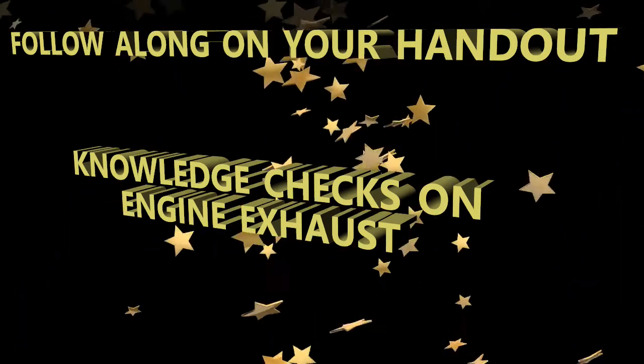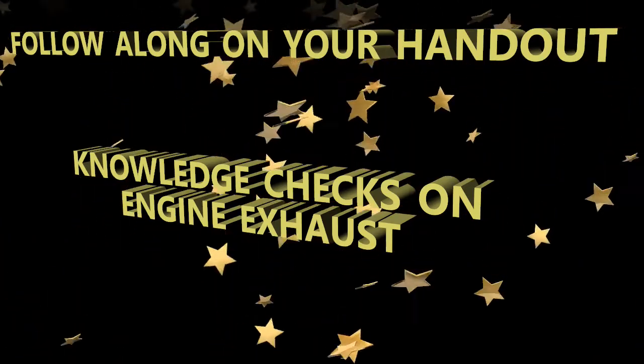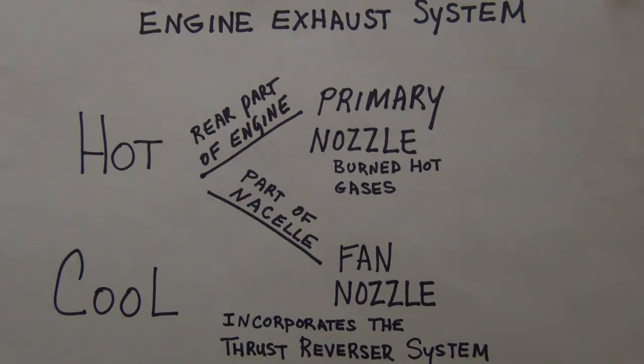All right, I mentioned the shutoff valve. We want to make sure that we have an operational test done on it to make sure it's functioning. And why is it so important? The answer is the second answer. It's there to stop the flow of hydraulic fluid to the hydraulic control unit. If there's some problem for whatever reason, we want to cut it off at its source, right? We don't want the flow to continue and have an actuation of the blocker doors when we didn't intend it.